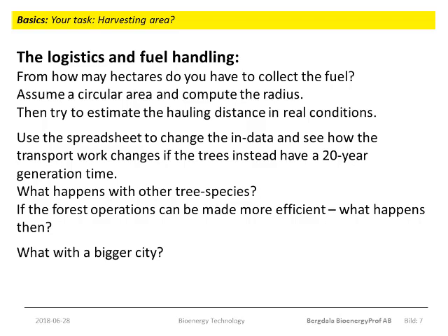If you did not use CHP technology, but used condensing power production instead, then the theoretical total efficiency of the plant, as seen in slide number 4, would be set by the Carnot limit. But on the other hand, you might be able to use a coolant temperature at some 10 to 15 degrees Celsius all around the year.